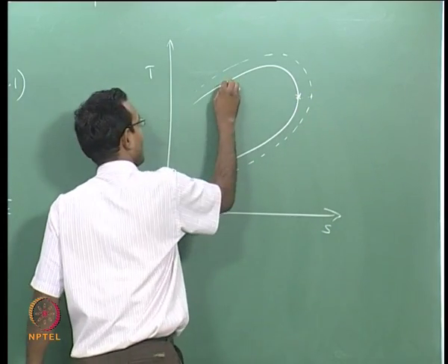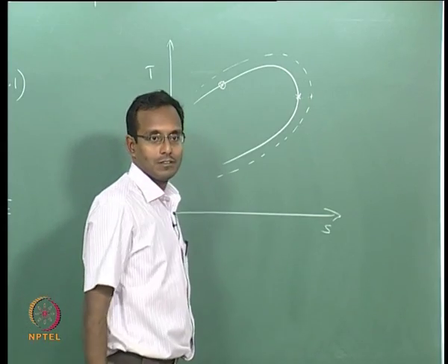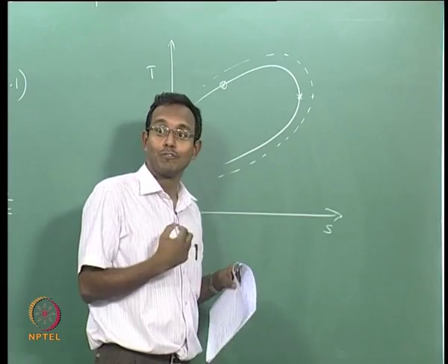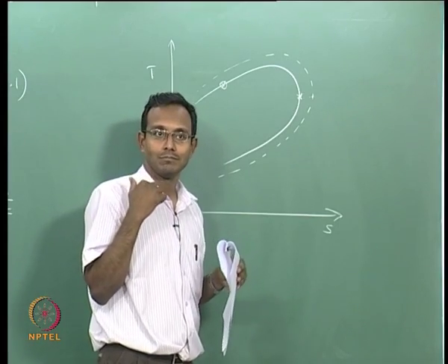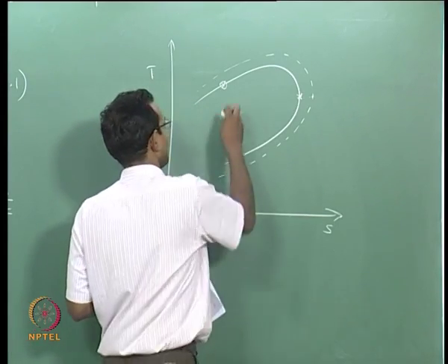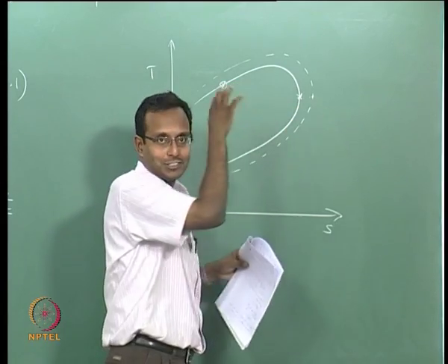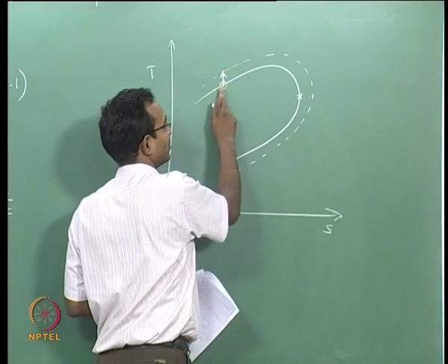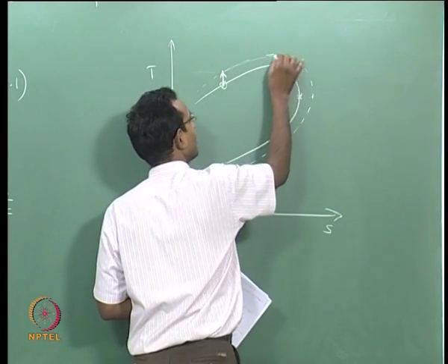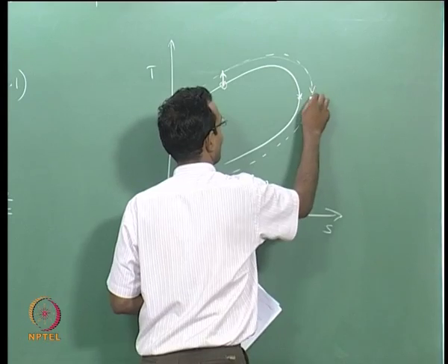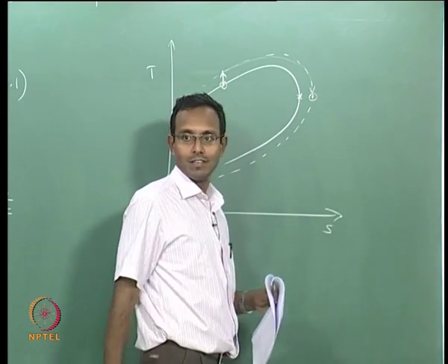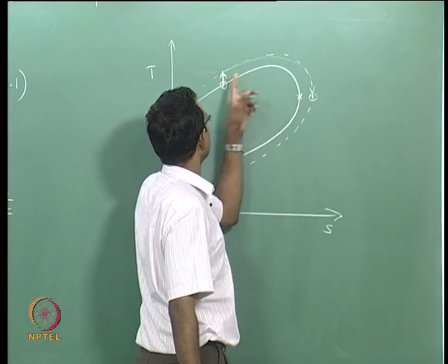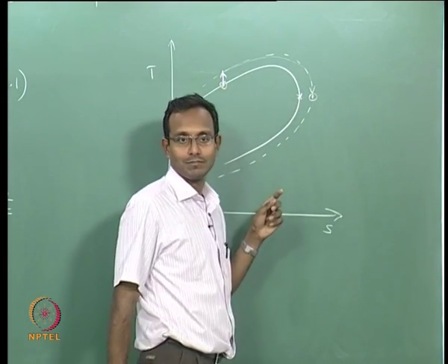So I say I started here, my M1 was initially here, let us say, and I added more fuel than this Q max value. Then immediately the whole flow field adjusts such that the flow at the inlet itself is decreased, it goes to the next curve, and then it goes along this curve to reach this point. This is your final state. It reaches M equal to 1, it is going to be choked, but it starts with a lesser mass flow rate.